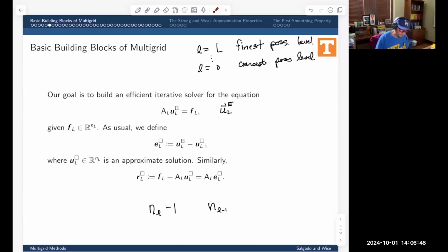Now the names and nomenclatures are sort of historically related. Stiffness refers to the stiffness of a spring system. U is the usual letter for displacement in the mechanics literature. And F is for force. So this is like a spring type equation, or at least the nomenclature reflects that it's a generalized elasticity equation. Stiffness matrix times the displacement vector equals the forcing vector, or the forcing load. The forcing vector is what's given, and the displacement is what must be determined in this whole problem setting.